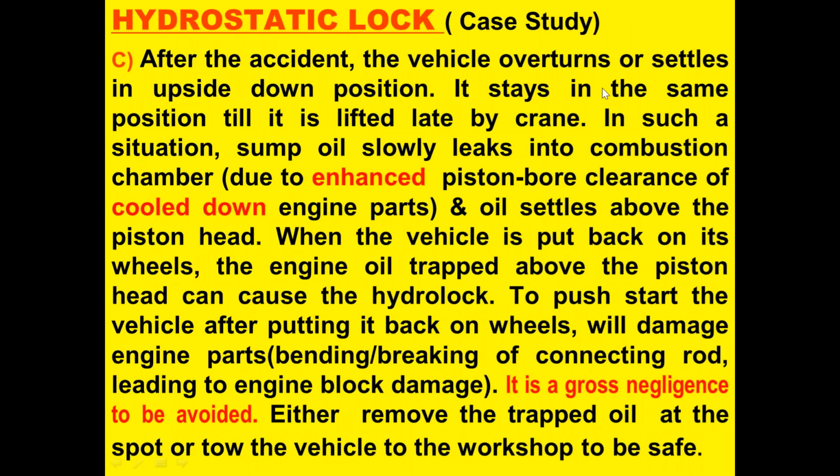After the accident, the vehicle overturns or settles in an upside down position. It stays in the same position till it is lifted later by crane. In such a situation, sump oil slowly leaks into the combustion chamber due to enhanced piston bore clearance of the cooled down engine parts. When the engine parts cool down, the piston bore clearance will increase, and that will allow the oil to go above the piston head and settle above the piston head.